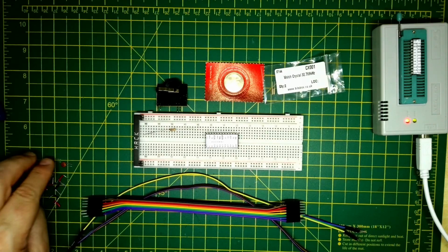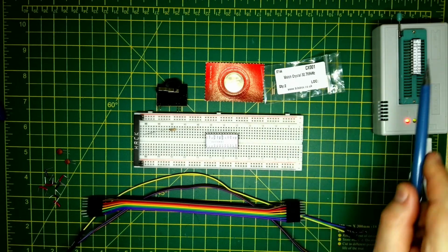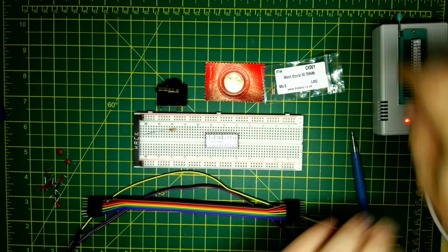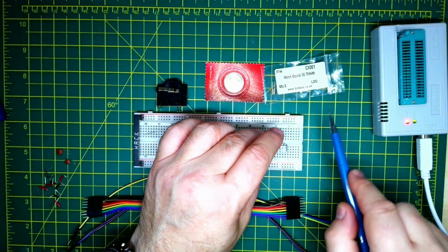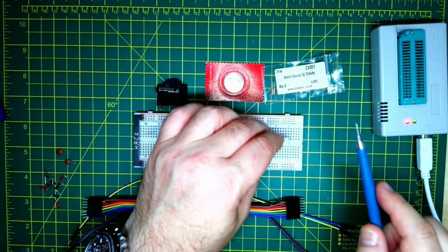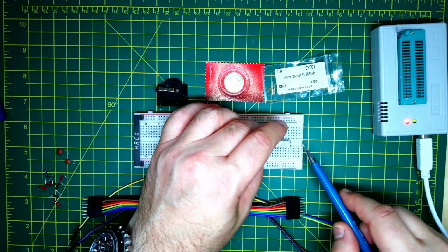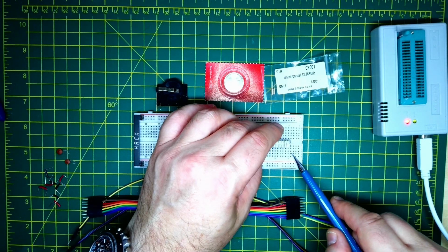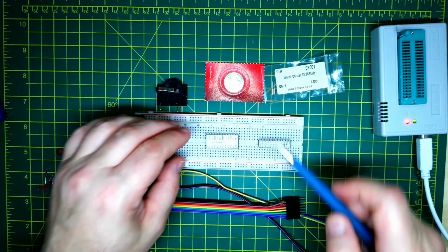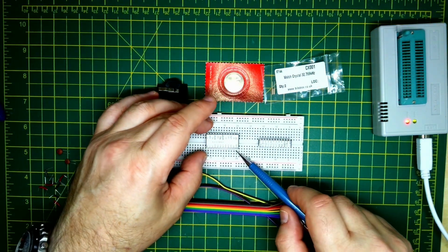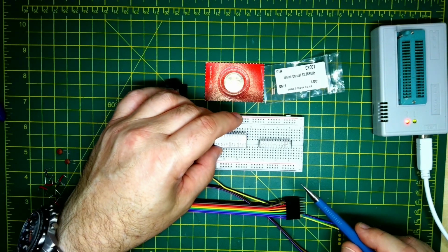Okay, so I've got some links here, and some decoupling capacitors that I've added onto here. I've put on the labels and we've programmed our PLD. So I'm just going to lay out the board now. In fact, the address bus and the I/O bus and everything else is going to be over this area when we plug this in. So we want to have the address lines over on the side here. We need to allow for our 4 address lines to come in over here. So we'll just put that there. And then this one, all the address lines are actually on this side, so it probably makes more sense to put this over on the other side here.